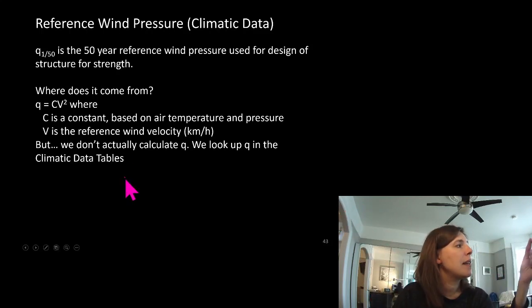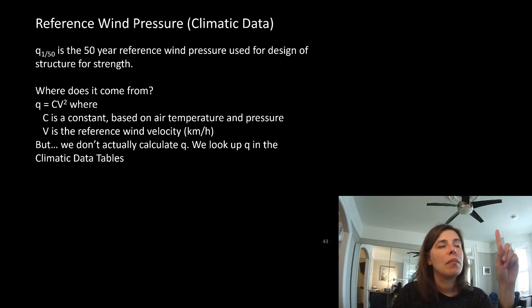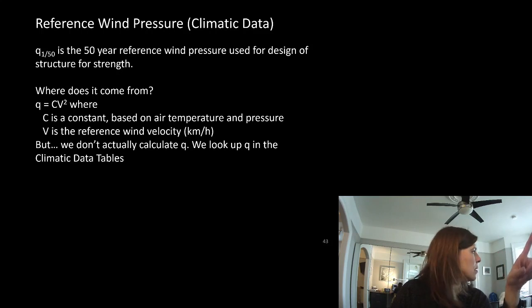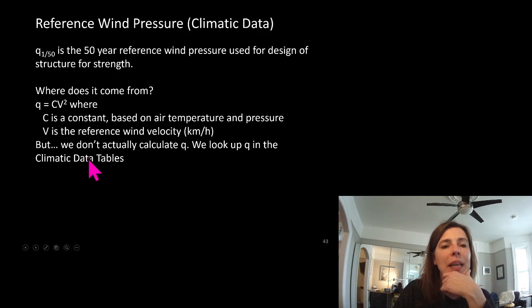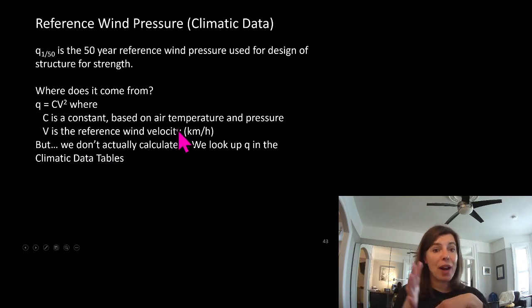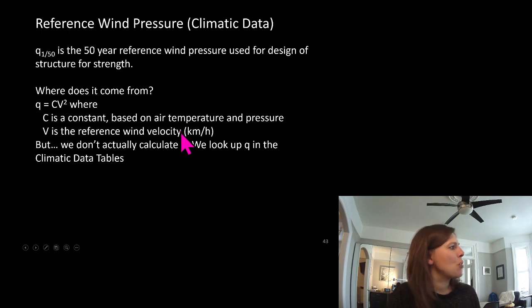But then there's a second thing that's different. We use a 1 hour gust, an hourly mean. So ours is the hourly mean wind pressure. So we say, okay, this is a pressure, and over an hour of a big storm, this is the average. We have other factors. That's where we use the gust factor to kind of help out those local gusts on it. The States use a 3 second value, right?